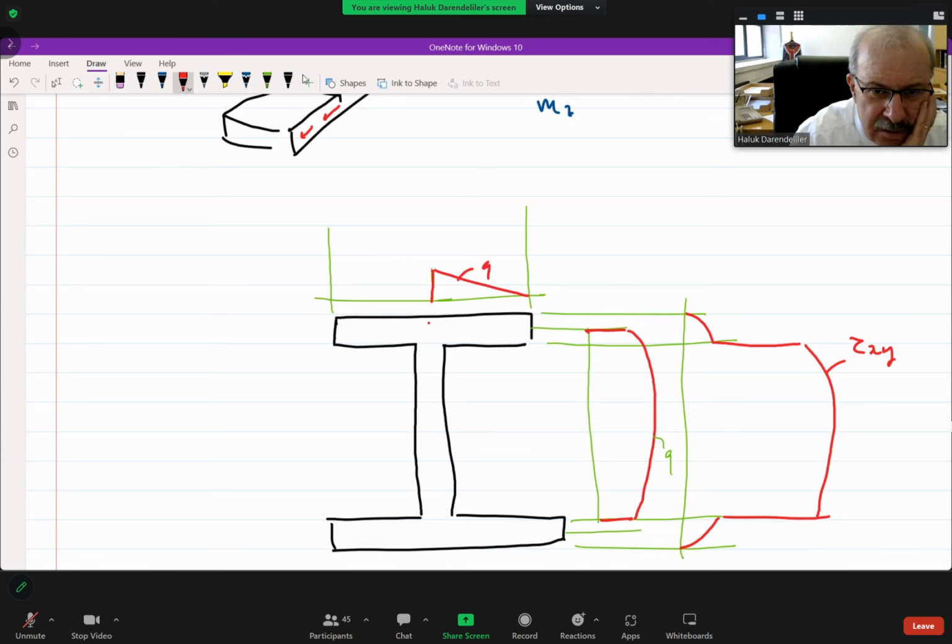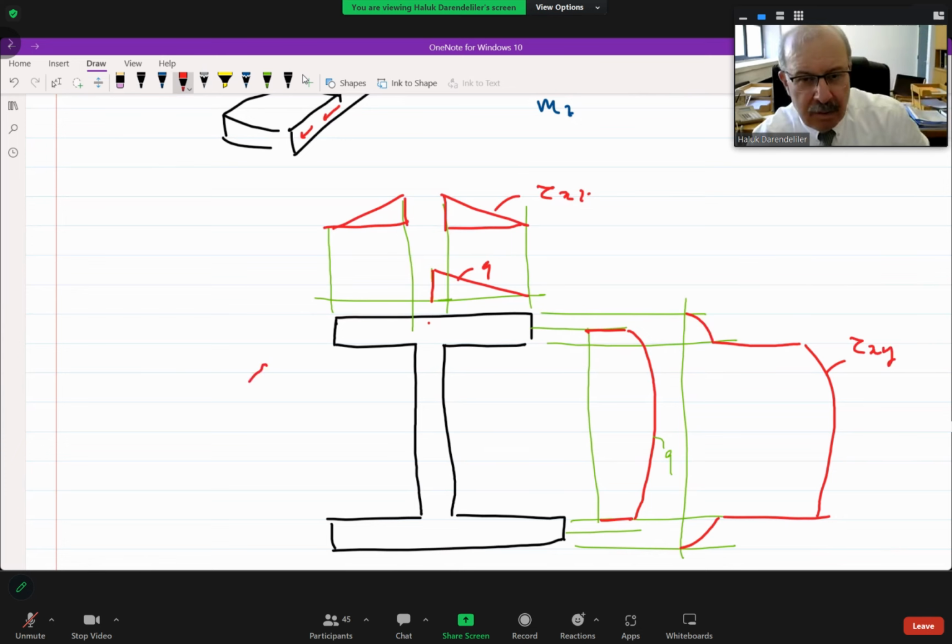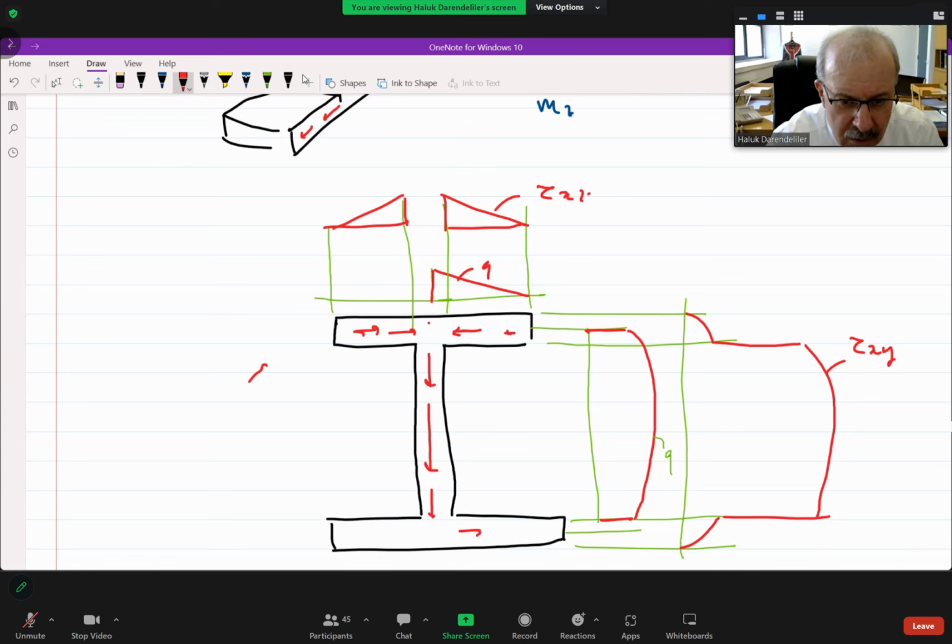And the shear stress for this part, as we have just determined from the above, has two different distributions. One of them is that, and the other one is that. So this is the tau xz distribution. Is this clear? Now, Q flows like that, greater here, smaller here, then turns back here, becomes very large here, smaller, then turns toward the ends and becomes 0 here, and turns to left and becomes 0 here. This is the direction of the shear flow with the same direction.